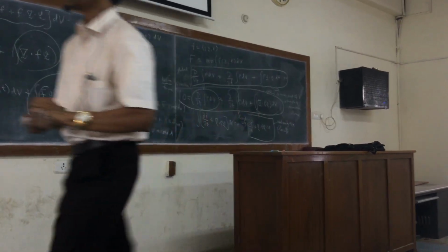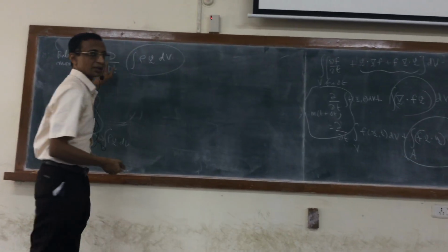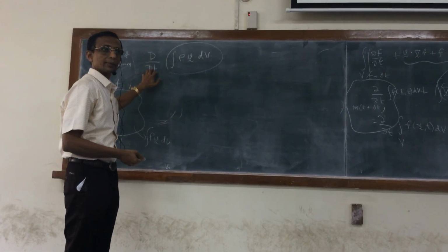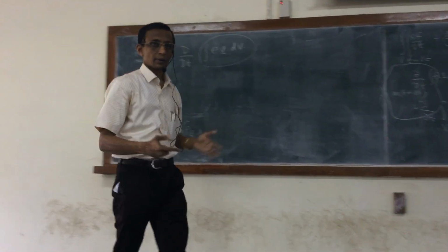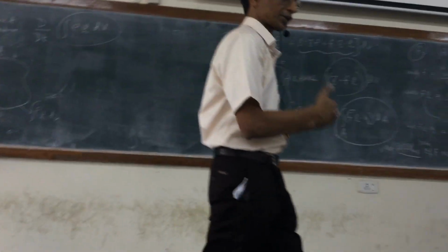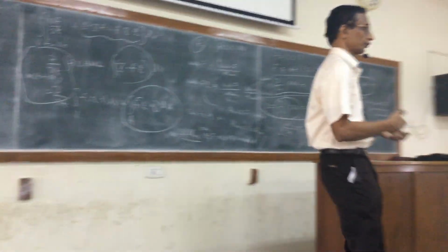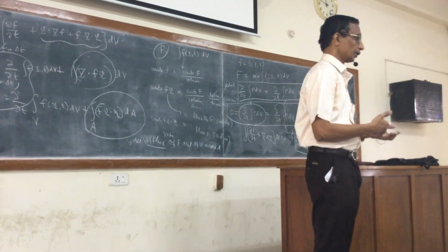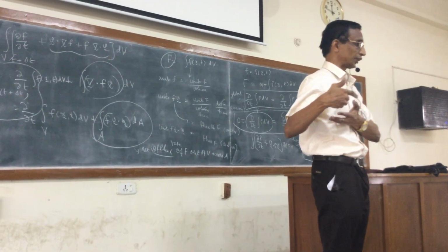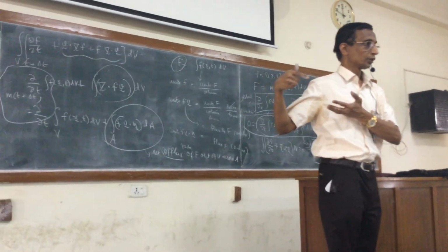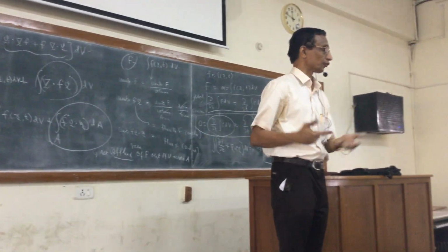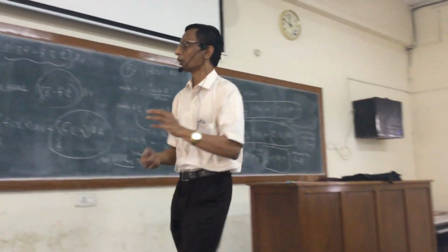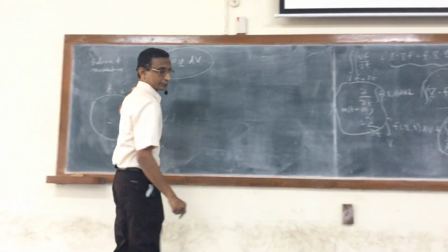So when I introduce a substantial derivative, immediately it means that I am now choosing this collection of fluid points in the region V at time t as the body of interest. So now I have to follow this body in motion. I am looking at the time rate of change of momentum of this body. That is the meaning of this.